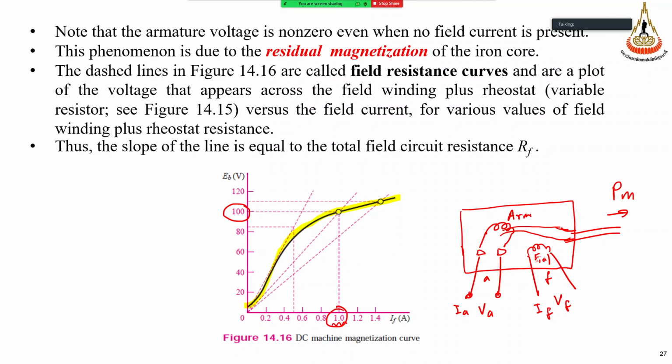Okay, I think you get some idea, right? The field current will affect the voltage here. The higher the field excitation, the higher the voltage, with this relation. It's not always this curve; this is just an example, a typical relation, for example only.